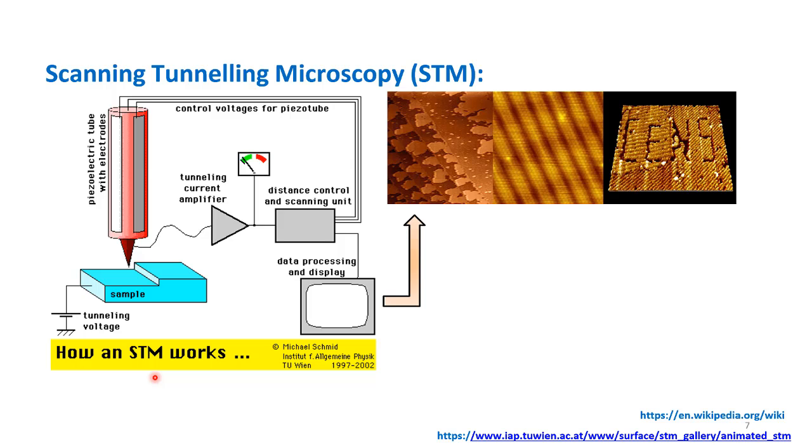This is the schematic of an STM. We have a probe here. This is a piezoelectric probe with electrodes, and it is connected with the voltage. And then here we have a sample. Suppose the sample is stepped like this. If the tip goes linearly, it will damage the tip. So in that case, we have two options. The first one is if we keep the height constant. If the tip reaches near a step, it will adjust itself because of the feedback loop.